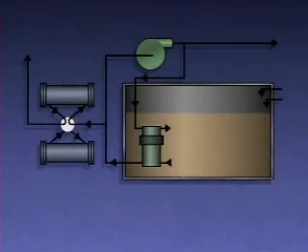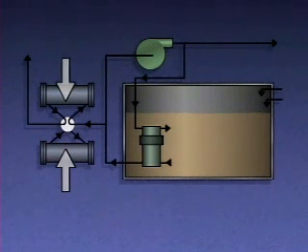There are as many types of lube oil systems as there are different turbine designs, but their principles of operation are similar. Lube oil systems provide oil for lubrication as well as for turbine control. In this part, we'll cover the part of the system that provides bearing lubrication. This illustration shows a typical turbine lube oil system. Its basic components are a reservoir, a main lube oil pump, a booster pump, and one or more oil coolers.